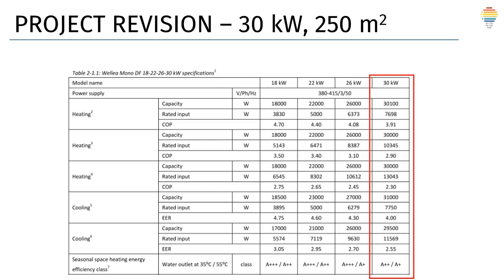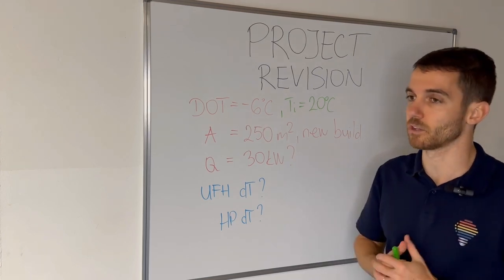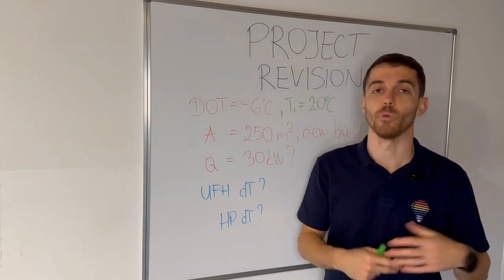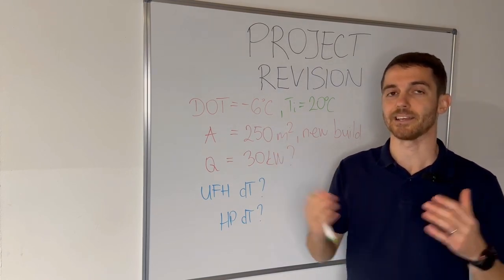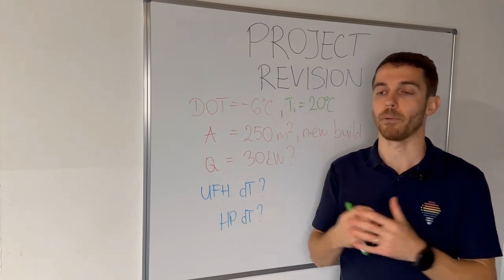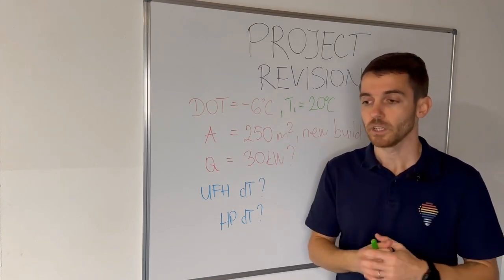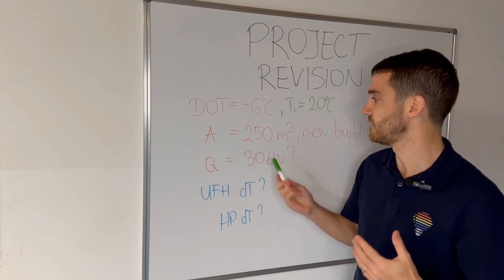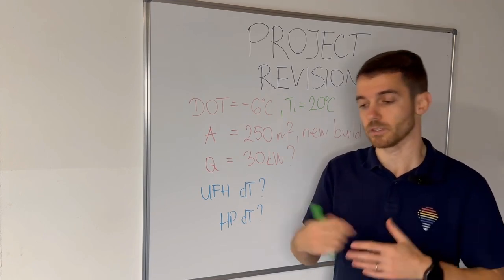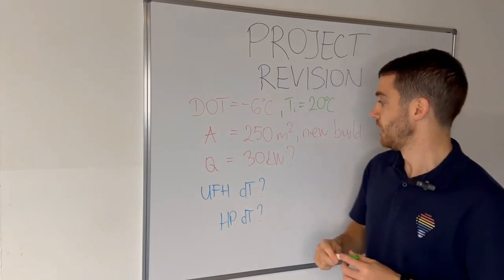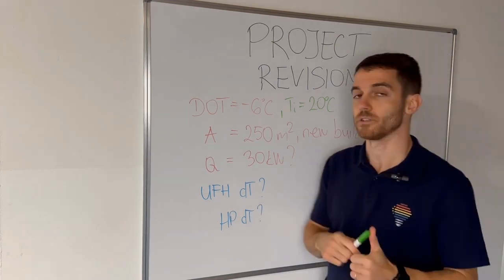If you ask me, there are not a lot of houses with more than 16 kilowatt heat loss, which is, let's say, the maximum heat pump capacity for residential buildings. So around 16, and this is not such a big house. For example, if it's 500 square meters, okay, we can deal with that. This is the first strange thing.